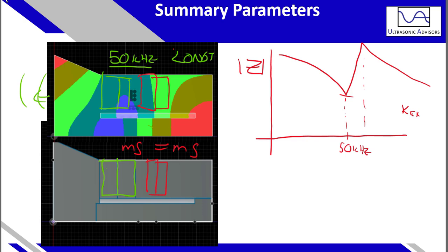However, the closer you put a material or a component near the nodal point, which is a high stress and strain location where you have more strain energy, the more the stiffness is going to play a larger role in determining the resonant frequency. Well, let's assume for this argument's sake that we have similar material properties in terms of mass and stiffness. So what will happen here is that if the mass and stiffness are the same, the resonant frequency won't change, because the resonant frequency is determined by mass and stiffness, not by placement, except in how it affects the effective mass and stiffness.